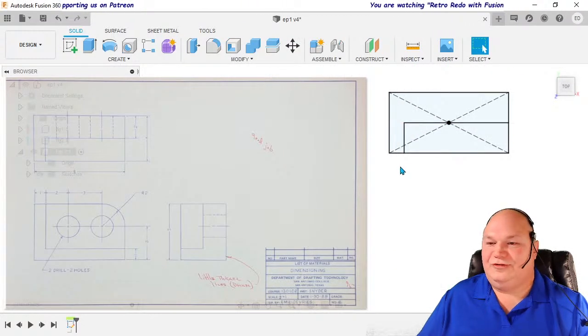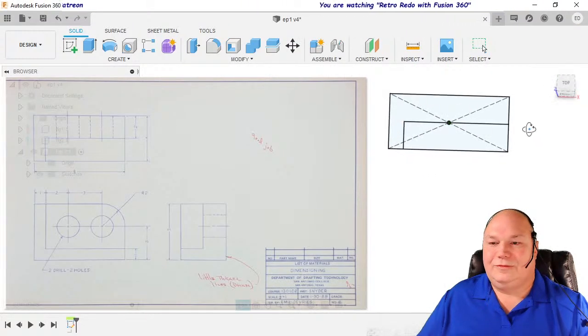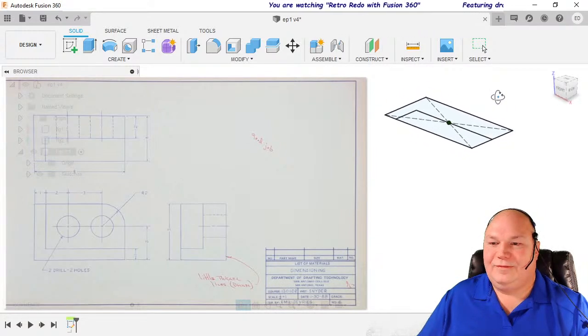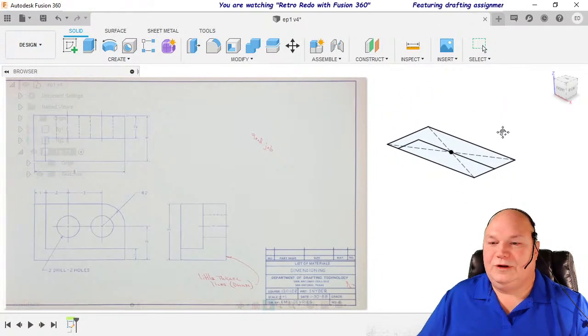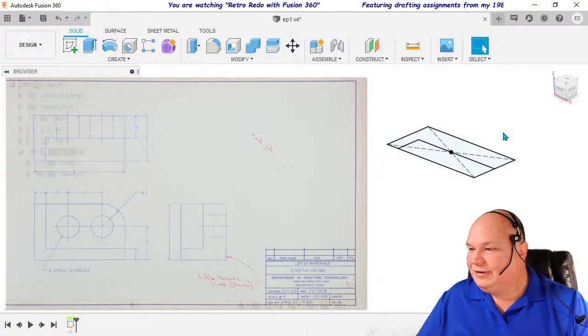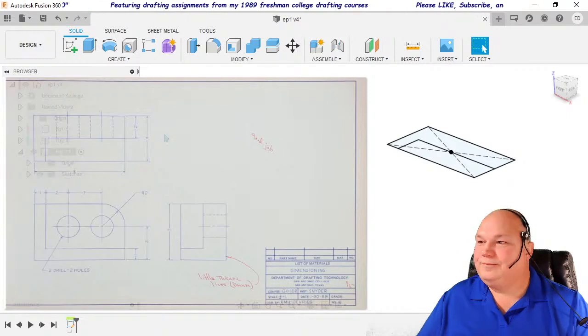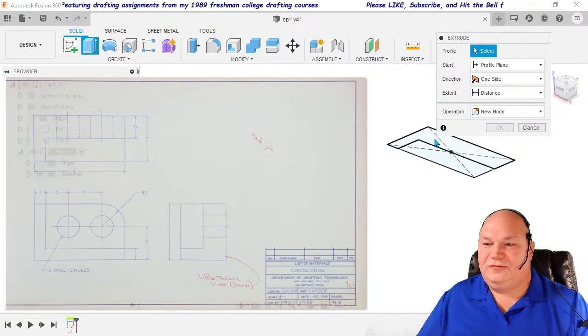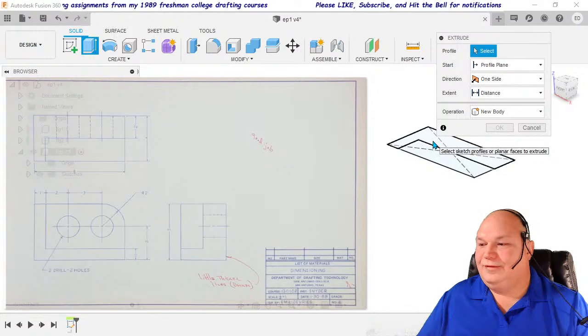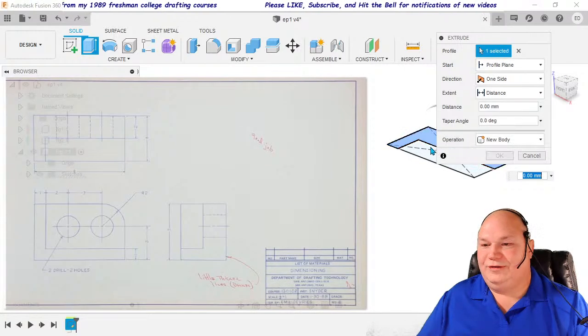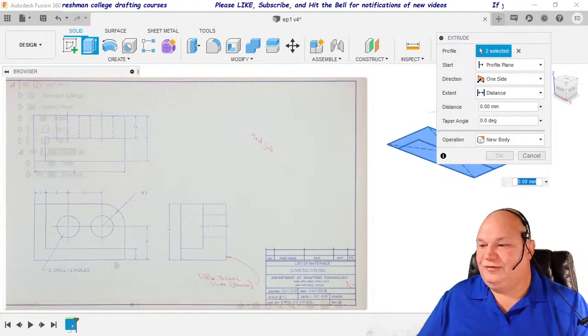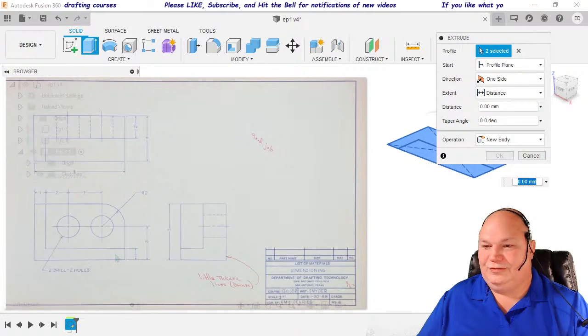Finish the sketch. Orbit around. Bring her down a little. Let's see, the overall height was supposed to be 5. I think that's what this says here, 5. Looks good enough, right? Extrude. Well, first off, we need the entire thickness to be extruded this one distance.